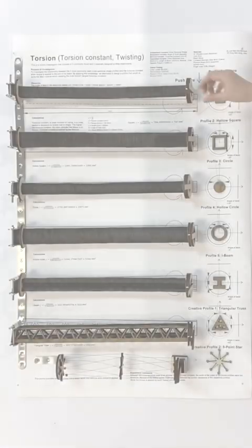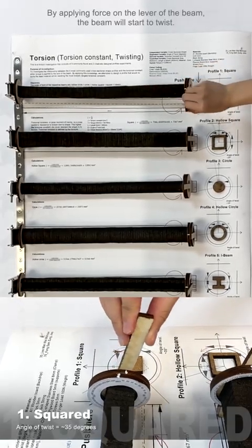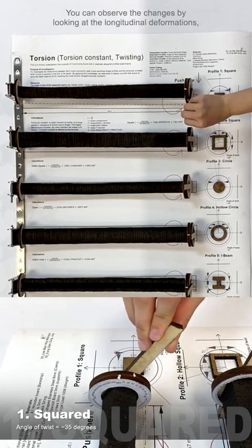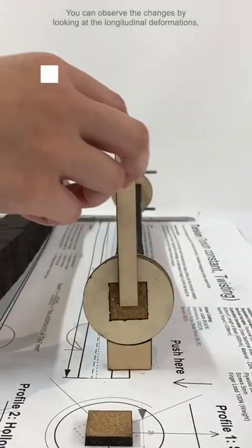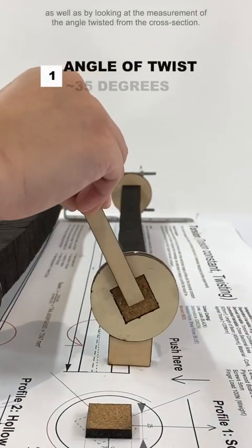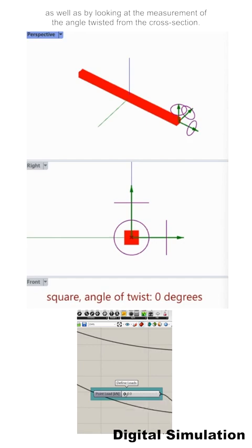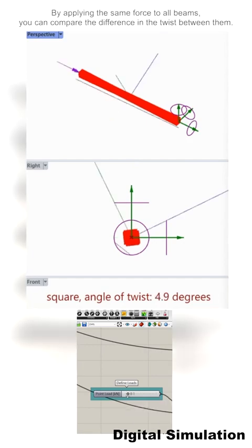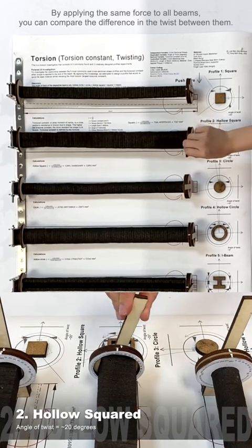results of each beam. By applying force on the lever, the beam will start to twist. You can observe the changes by looking at the longitudinal deformations, as well as by looking at the measurement of the angle of twist from the cross-section. By applying the same force to all beams, you can compare the difference in twist between them.